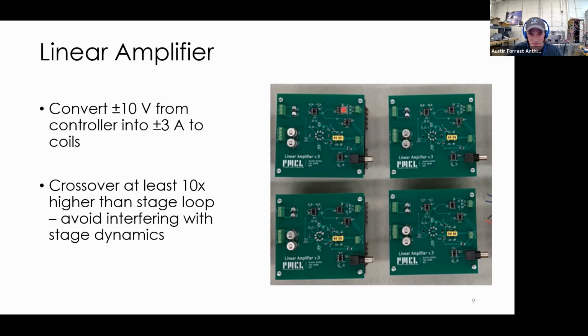You can see, here's the input reference. This is the control stage going into the power stage, the current output, and then the feedback to close the loop. This is where you put the power rails in, and these are bypass capacitors, which smooth any deviations in the power input. We added a BNC connection here, which takes the current output and converts it to a voltage that we can easily look at on a scope, which turned out to be very convenient.